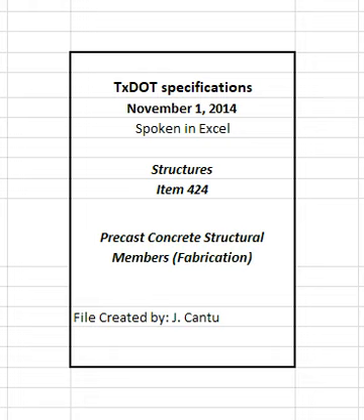4.2.5.3.2.2 Surface vibrators. Use vibratory screeds to consolidate thin sections. Move vibratory screeds at a rate that will bring enough mortar to the surface to embed and cover the coarse aggregate. Do not over-vibrate by causing an excessive amount of mortar to be brought to the surface.